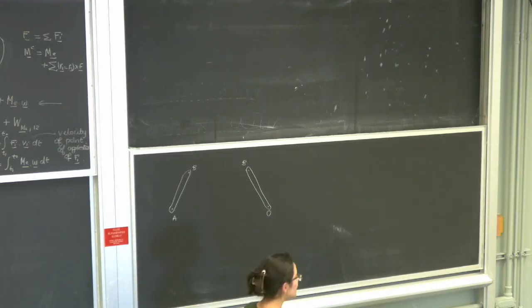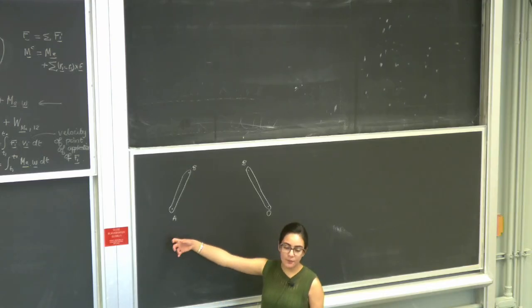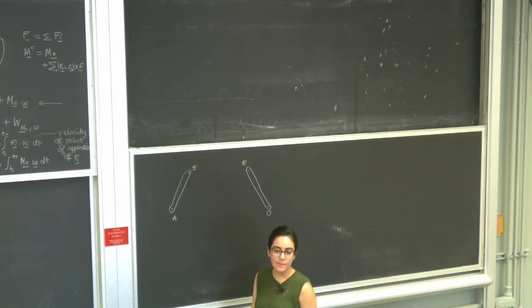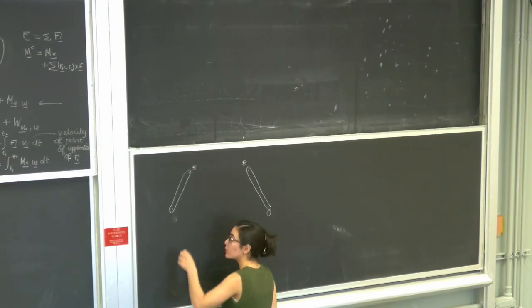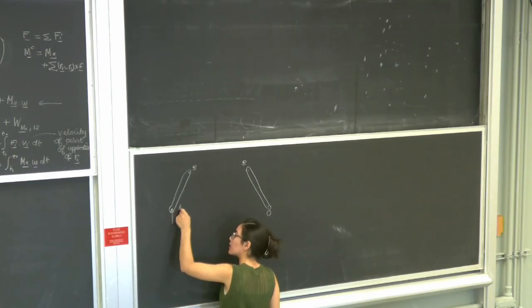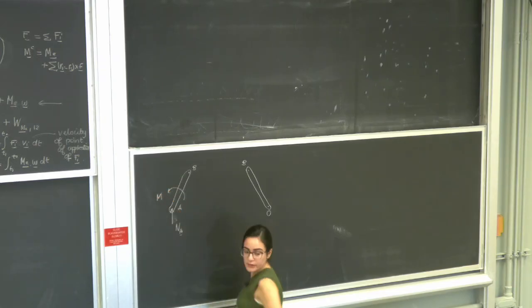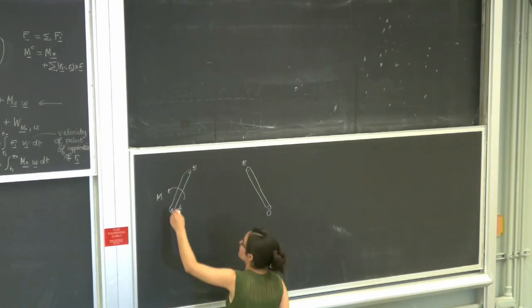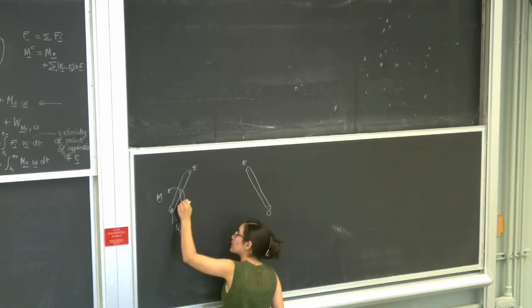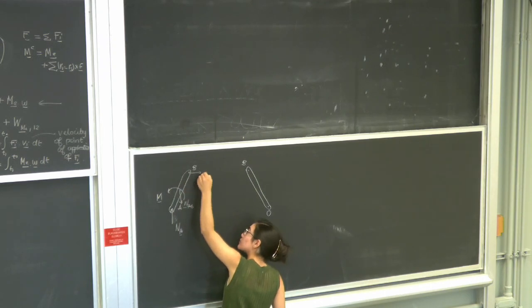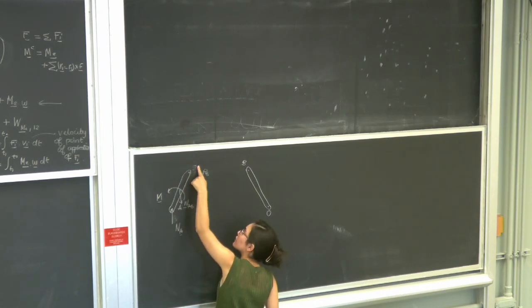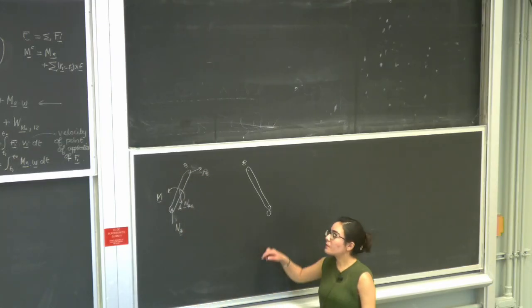Okay, let's draw the free body diagrams together. What are the forces acting on bar AB? Reaction force at A. Is it the reaction force or a normal force? Normal force, because it's a roller at A. So NA, we have the couple M. What else? Weight. And reaction force at B. It's not vertical, so RB.